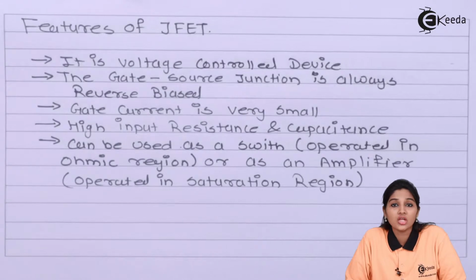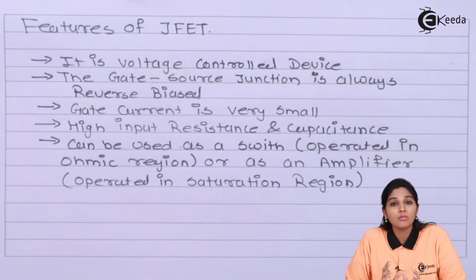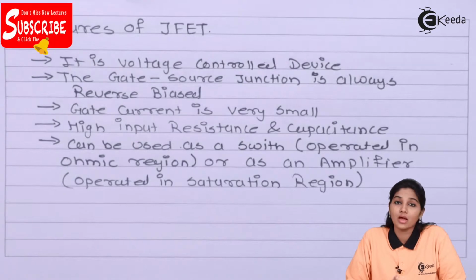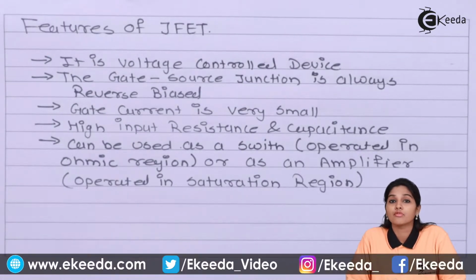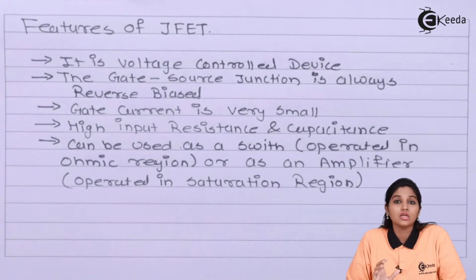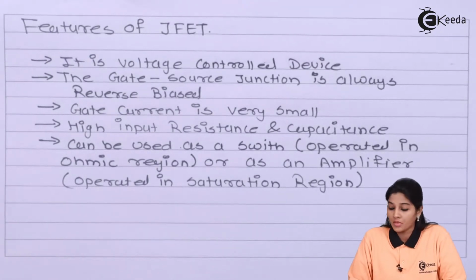If we consider N-channel JFET, then it consists of N-channel semiconducting bar and heavily doped P region, and that forms a PN junction. So we need to make that PN junction reverse bias by applying either a negative VGS or by applying a positive drain to source voltage between drain and source terminal. So even if a positive drain to source voltage is applied with gate terminal open, it can cause the effect of reverse biasing of gate to source voltage because of the channel resistance RB.